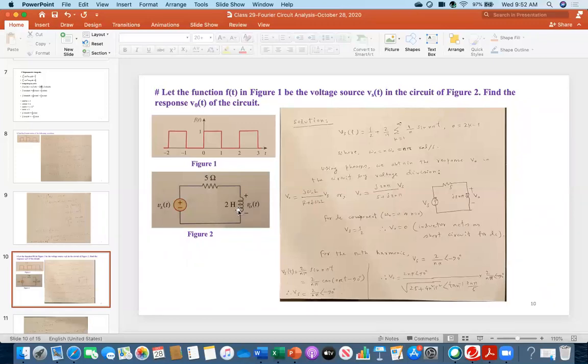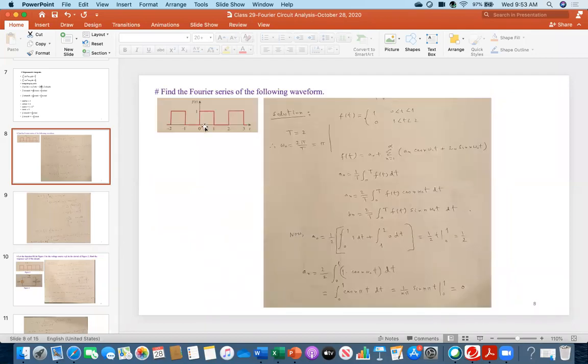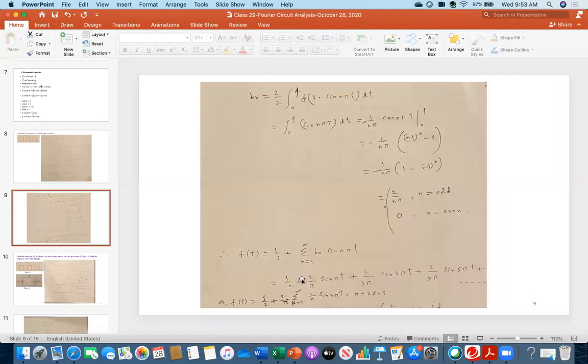Now, first of all, if you see this type of problem, where this is the input signal for this circuit or any circuit, your first task is to apply the Fourier technique. First, you have to convert it into a sine or cosine form or a DC signal. For example, in the previous case, exactly that was the function, and we got this result.